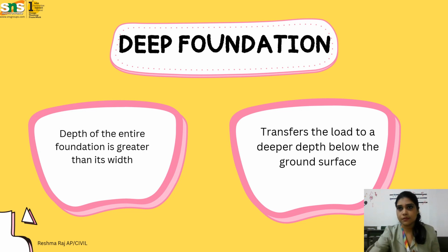Next, the very important property is the cost and time of the deep foundation. Deep foundations are generally more expensive and time consuming to construct compared to shallow foundation. Of course, why we are going for the deep foundation is because the soil in that area is not good, meaning it will be weak or compressible in nature. It will be cohesive or cohesionless. In such cases, we go for deep foundation.